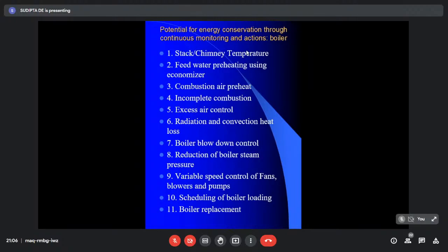Okay, this is rather simpler to understand because there is not much engineering or technology in it. The only thing is, as the inside temperature may be more than 1000 degrees Celsius, and the normal atmospheric outside temperature is around 25 degrees Celsius, you can have an idea how much temperature difference there is. So outside the boiler, you will always find heavy insulation. Insulation bricks are there, and design of insulation is also a technology. I mean, proper insulation design, making the thickness and proper material in between. There is an air gap. All these things are part of boiler design.